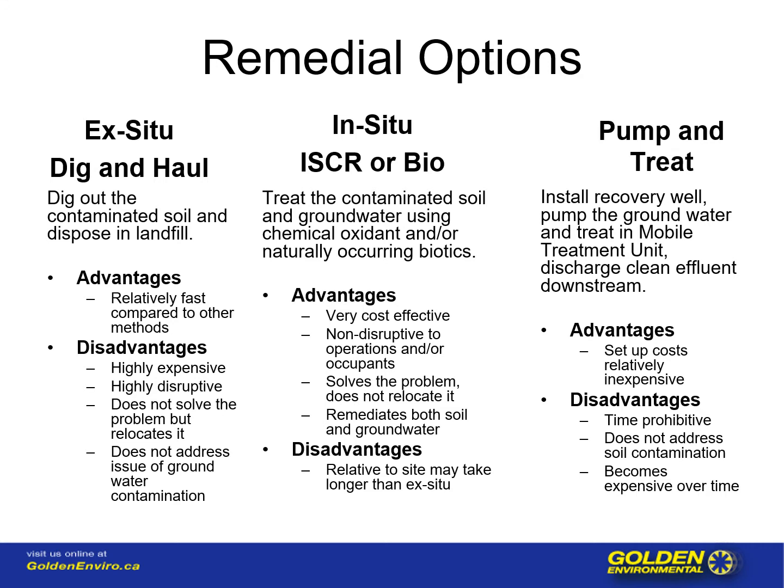In order to use the existing microbes within a site, one must stimulate them by adding nutrients like nitrates and phosphates, and also supplying oxygen to them. Stimulating the microbes is a very delicate procedure in that if you overstimulate them with too much oxygen, which can be used by a chemical oxidant, you can end up killing off microbes rather than just stimulating them. We highly recommend that if one is going to choose bioremediation, that they culture a batch of microbes and then inoculate the site accordingly.